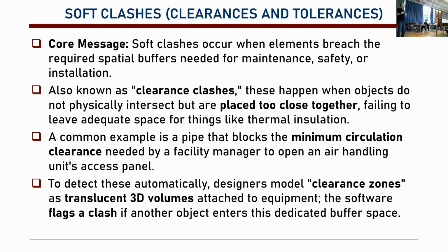And sometimes clearance is about installation, as in this case, because these pipes have hangers. Do you see the hangers? Hangers are connected to the structural system. You need a space to be able to put that hanger, attach it, and adjust it.